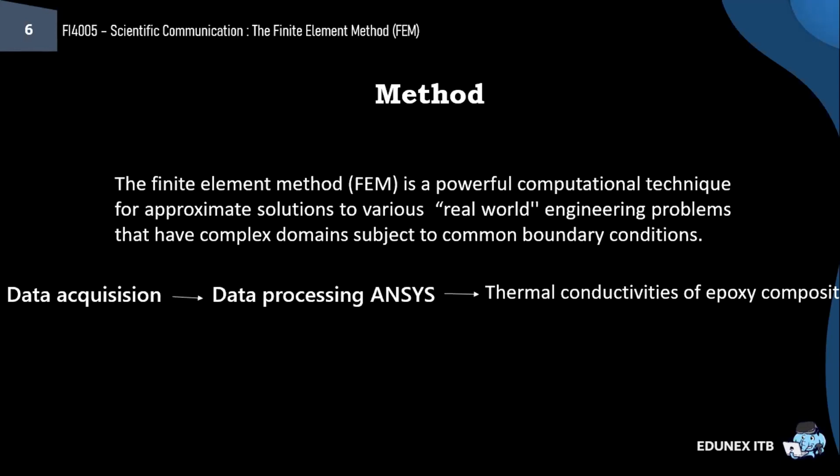make a thermal analysis, three-dimensional physical models with spheres in a lattice array have been used to simulate the microstructure of composite material for different filler concentrations. Furthermore, the effective thermal conductivity of this epoxy composite filled with fine wood, up to about 36% by volume, is numerically determined using ANSYS.